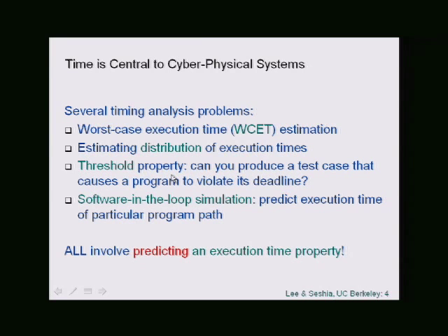And a lot of people who build real systems, you might have heard of hardware-in-the-loop simulation, where when they've written the code, they run it on the actual platform and simulate it along with either a model or with the actual artifact. But increasingly, hardware-in-the-loop simulation is too late to make sure that the system works correctly. So people do what is called software-in-the-loop simulation.